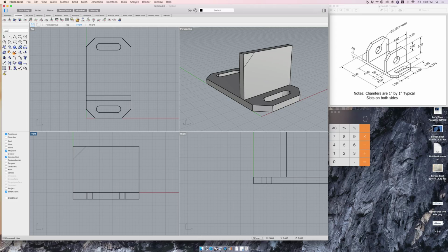There's a line, there's a line. And you know what? This time I'm going to do something different. It's called a polyline. And I'm going to draw actually a triangle. So down, down, down, down. Perfect. So you'll see that's actually a triangular shape. I'm going to go ahead and mirror that real quick. This thing. And then I want to mirror across the midpoint. Perfect. I can use those objects to cut.